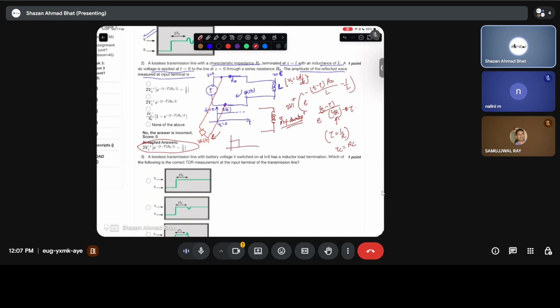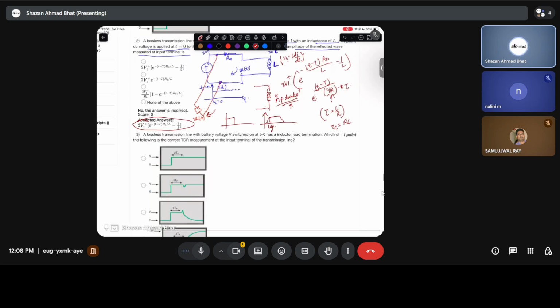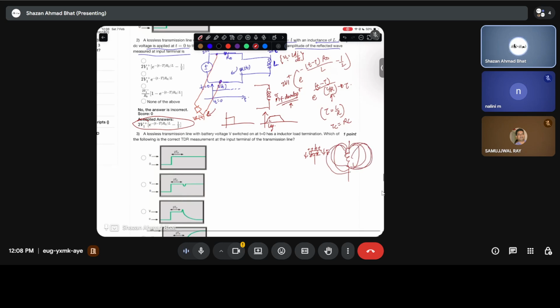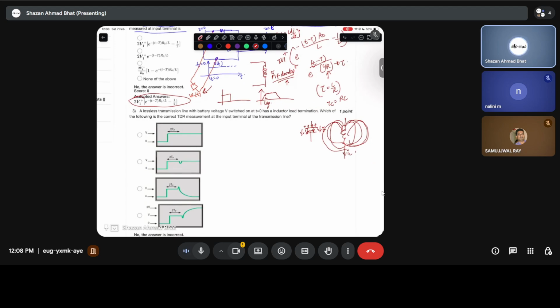That means if you give a voltage pulse like this, you will get something like this, which is basically a lag, with a rise time and fall time always associated because of this inductive effect, because there is a rise time and fall time associated with the developing of the magnetic field across the inductor, similar to the charging and discharging of a capacitor. For the capacitor, the electrostatic field is there because of positive and negative plates. But for an inductor, a magnetic field is developed. These are the magnetic field lines emanating from an inductor because of the current flow across it.